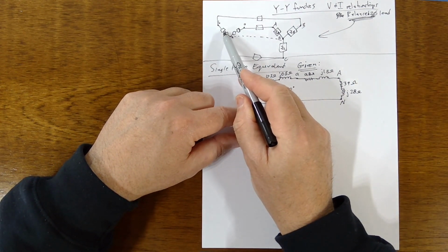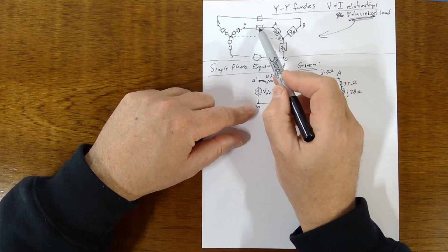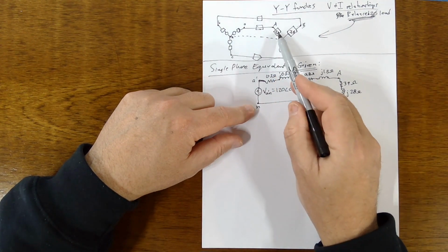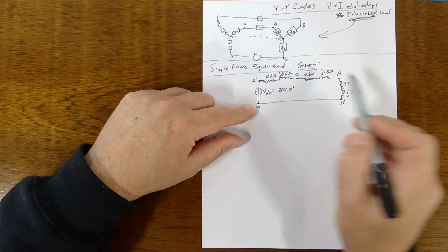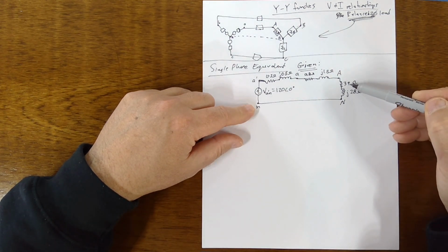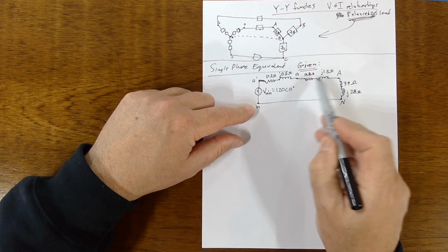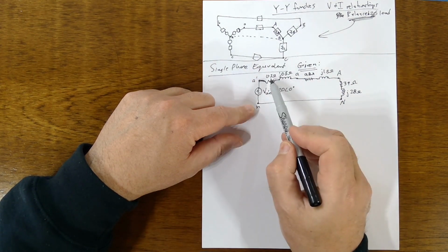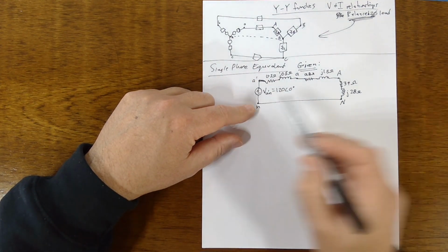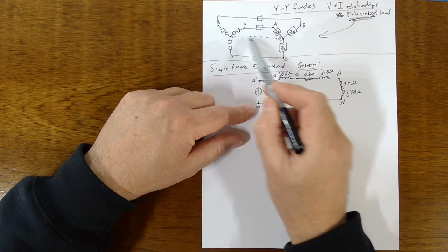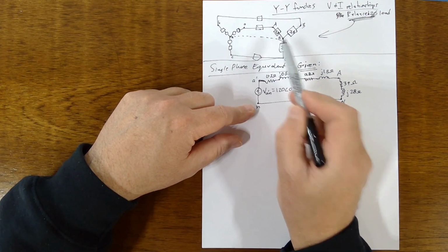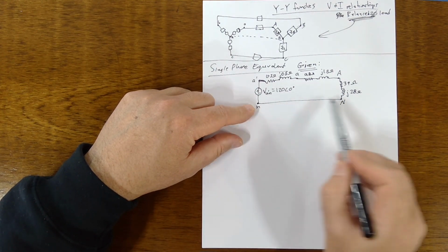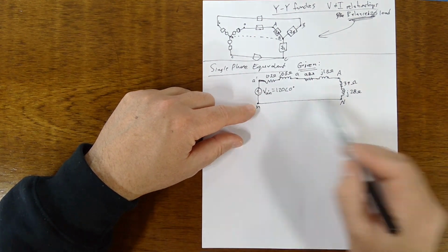Then the impedance in the generator is these two items. The impedance in this distribution line is these two items. And the impedance in this load, ZA, is these two items. And the magnitudes reflect that. Like the load is 39 and 28. That's a pretty big number compared to 0.8 and 1.5, the distribution line. And then an even smaller number is the wires inside the motor, this 0.2 and 0.5. Okay. So we're looking at the single-phase equivalent, just this loop right in here. Here we're modeling, and this is a model, right? We're modeling this center conductor as the return path for the current around this A loop.